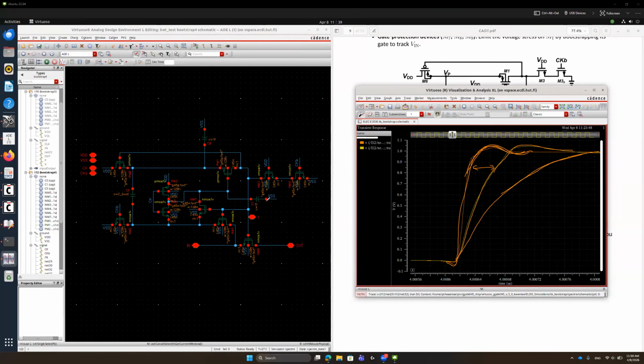Then the question is that, do we need to add this kind of capacitances? In practice, no, because after we fabricate the chip, there will be some parasitic caps added in the layout, after doing layout. So, yeah, by that effect, those individual nodes will be stabilized one step further.